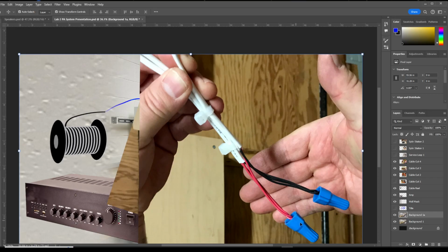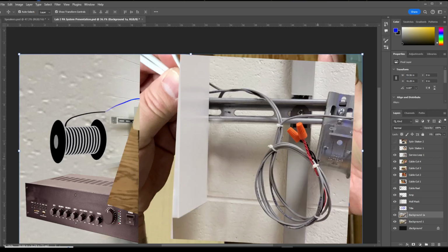Now, I noticed that some people just keep twisting all those things with the insulation, those jacketed wires. No, do not twist those. Just leave them the way you can see them here. You might want to twist just the end of it and just apply those connectors on. And after you do that, you can roll the whole thing into one beautiful service loop.